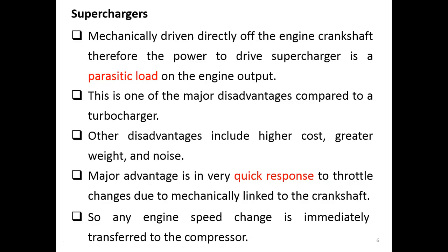So this is one of the major disadvantages compared to the turbochargers, where we use the energy from the exhaust gas. Other disadvantages of the supercharger include the higher cost, the greater weight, and also the noise. Because you have to install one more device into your engines, your engine chassis has to carry more weight because of the superchargers. And when it operates, it creates noise in your engines.